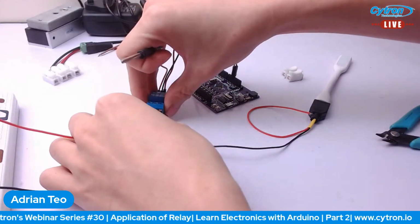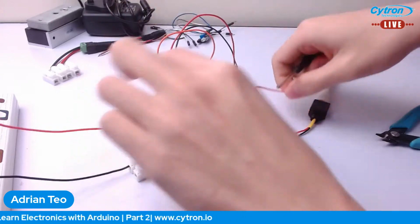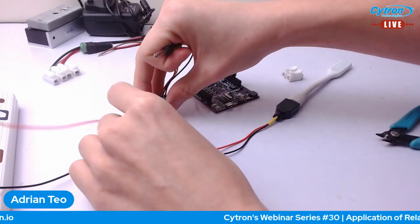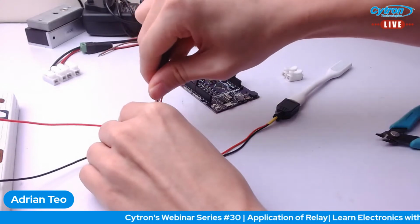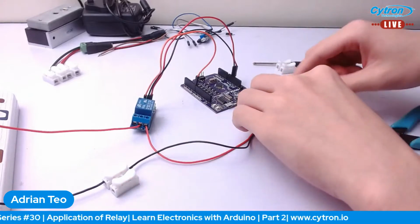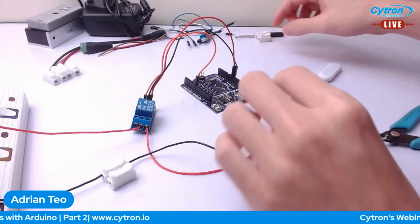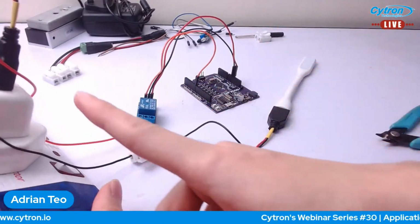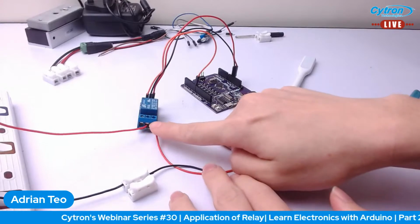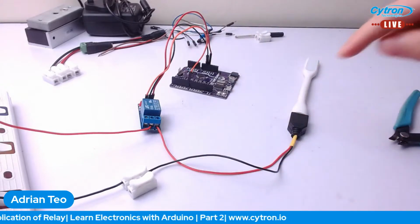So back to the relay, plug it in, screw it in. If you want to let students try using relay, I suggest trying something simple like turning on and off an LED, so that they understand the concept of a relay before you introduce them to plugs of 5 volt. But of course DC is still safer than using AC. So now I have my positive connected here, and then my positive between this is connected to the relay. I am going to power up my Maker Uno right now.